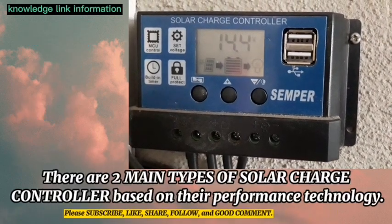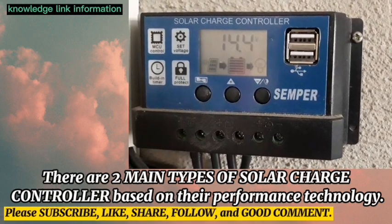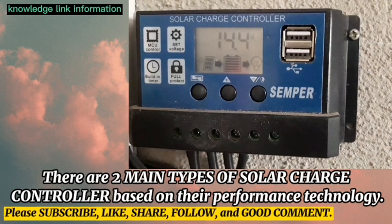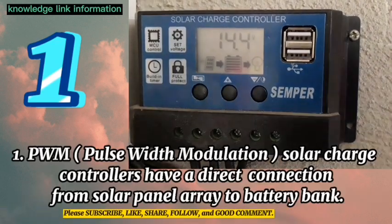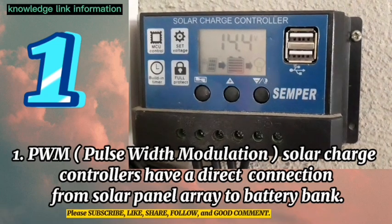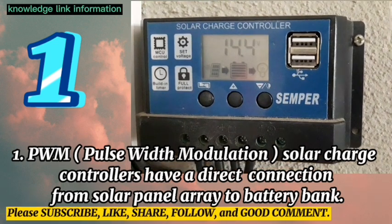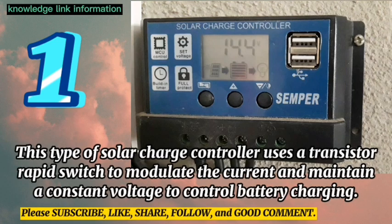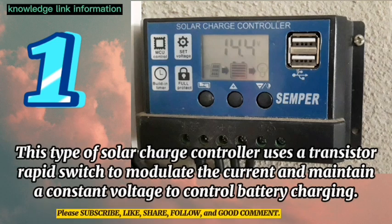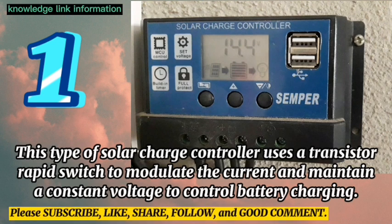There are 2 main types of solar charge controller based on their performance technology. Number 1. PWM, pulse width modulation. This solar charge controller has a direct connection from the solar panel array to the battery bank. This type uses a transistor rapid switch to modulate the current and maintain a constant voltage to control battery charging.